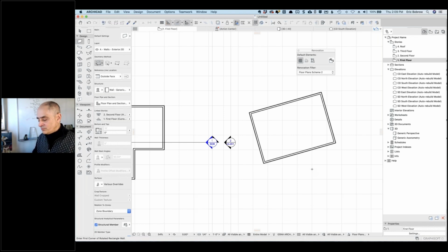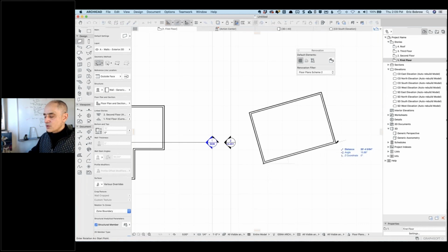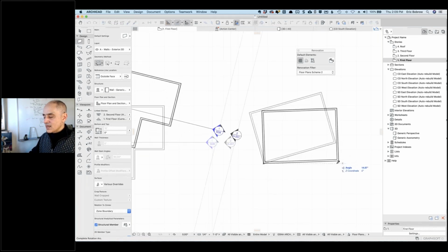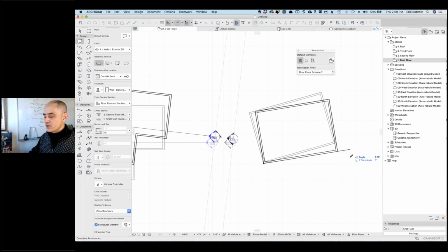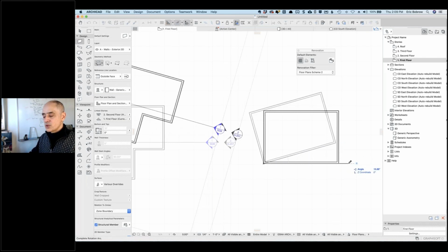So first of all, if I wanted to rotate this view so that this was just more convenient to work with, I can use, down in the lower left of your screen, this thing that has an orientation. It says orientation 0. And I can say I'd like to set the orientation graphically and click on, for example, a corner and another corner, and then rotate it down. And you can see it's giving me a preview, and I can snap, of course, to the axis.